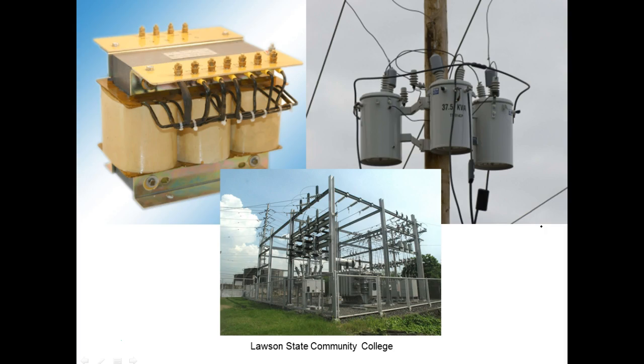So these are some three-phase transformers. This is probably one of the most popular. These would be a three-phase transformer. Now, the problem with this is that if you lose one of your transformers, you have to replace the other transformer. Most of the time, people that run three-phase don't actually have a single three-phase transformer, but three single-phase transformers. That way, if a transformer goes out, they can just replace one transformer, right? That makes sense. And these substations are nothing but transformers.